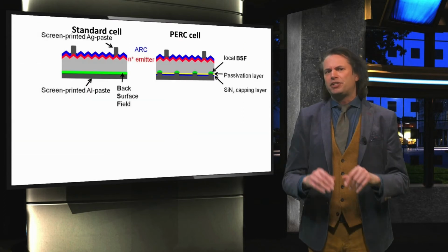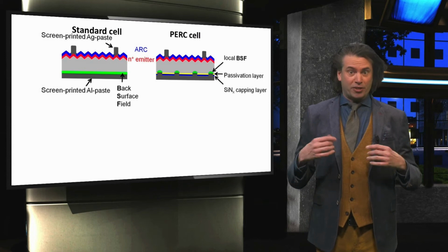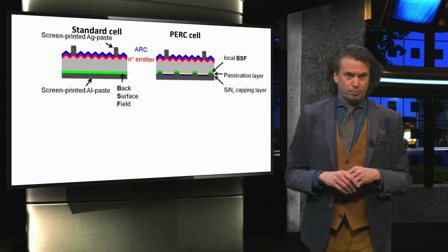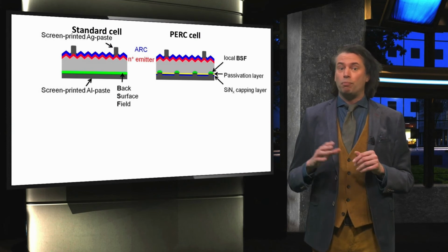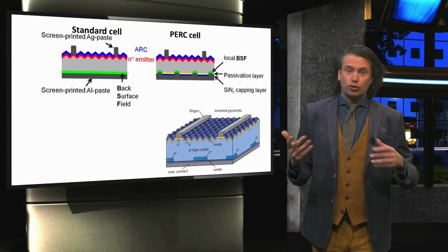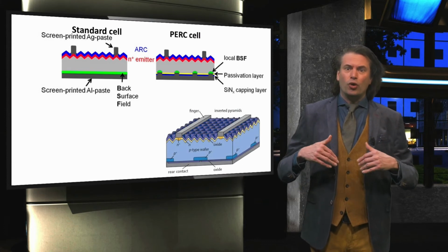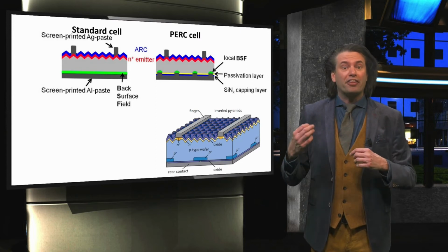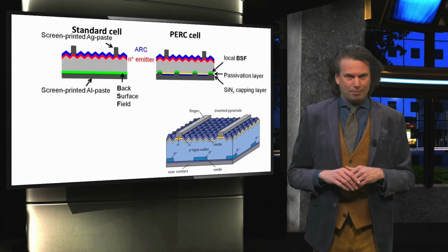Apart from these general design considerations, we looked at some advanced concepts for crystalline silicon solar cells. The PERC technology is now the most produced solar cell on multicrystalline silicon. We have also seen that the TOPCon design can replace the back surface field and localized contacts with an ultra-thin tunneling layer and full metallization at the back.